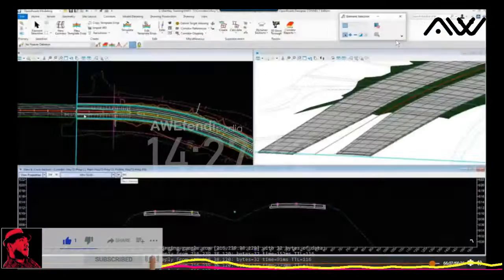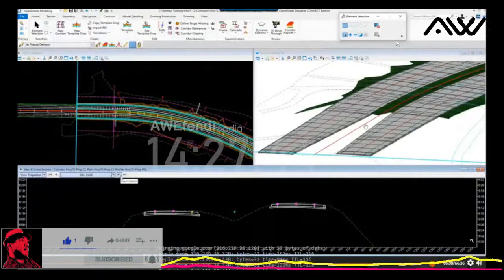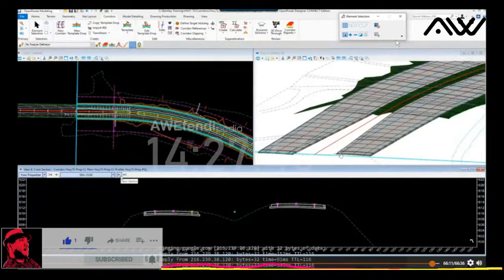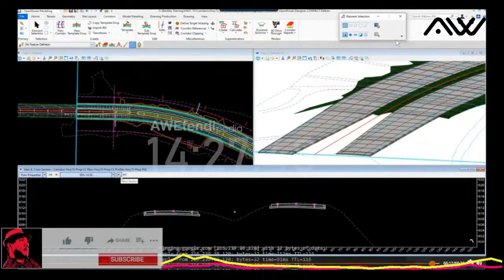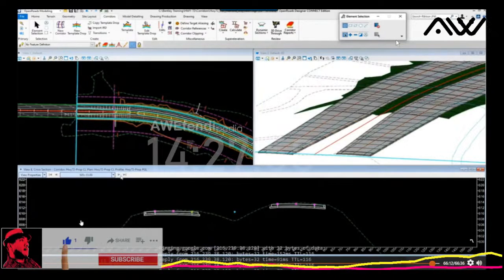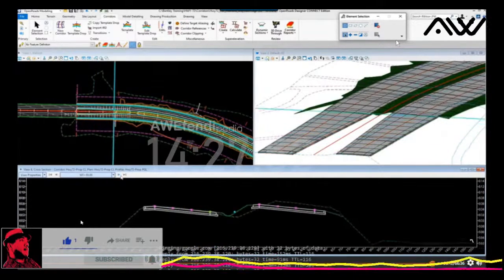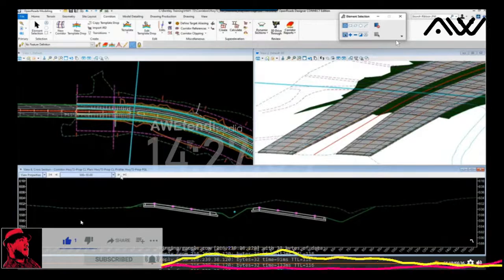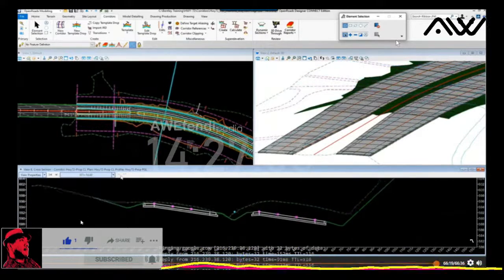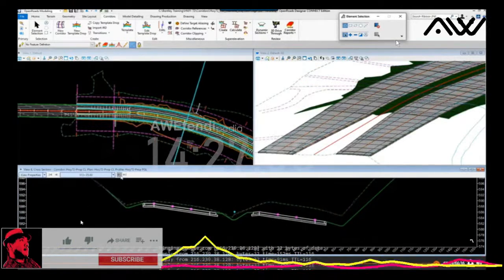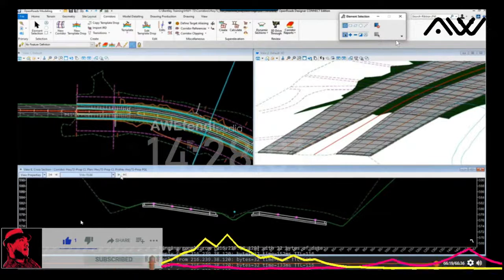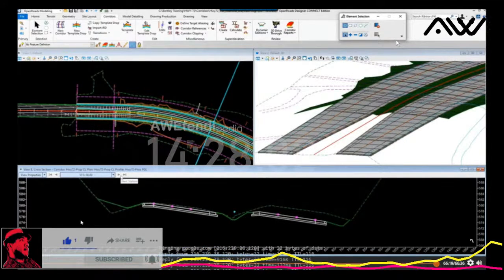You see it in 3D here. And we created control lines to control the horizontal tapers as well as the vertical transition in the bifurcation between the two roadways. And so as we run through this series, as we walk down these cross sections, you can see how the pavement is going to interact when Scott builds this corridor next week, okay? All right, so